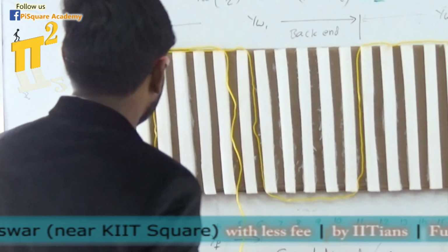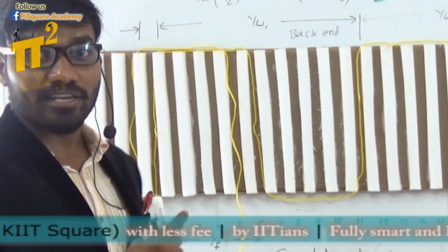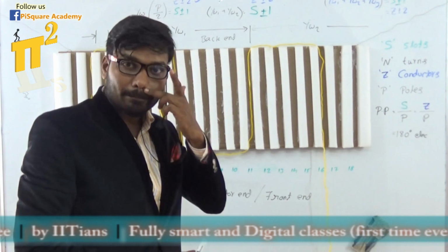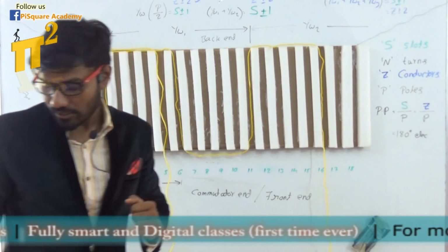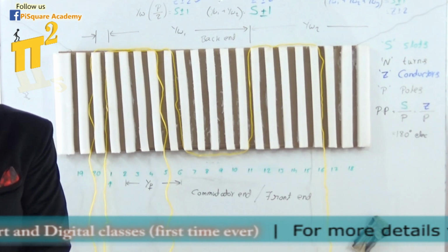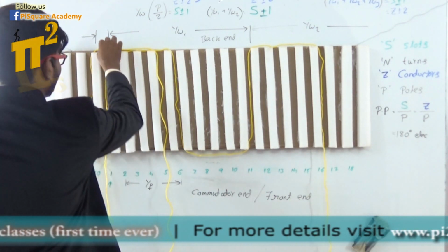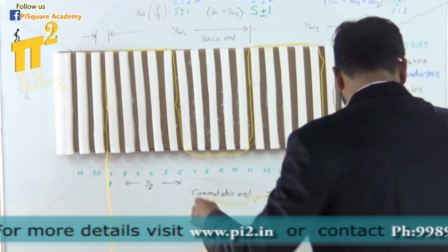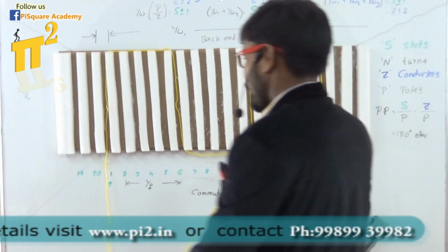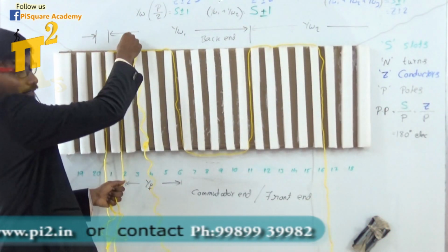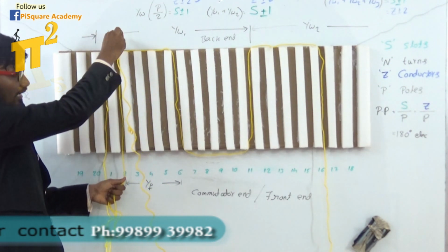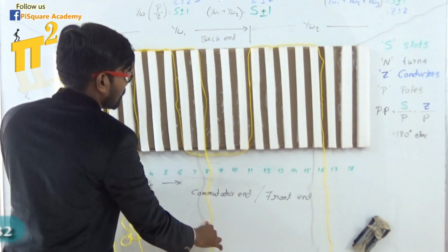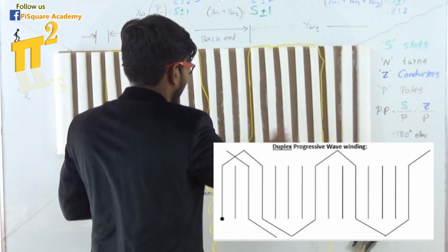Now, there is another thing called singly re-entrant and doubly re-entrant. But before we go to that, I think we missed multiplex winding. So far we have seen simplex winding. What is duplex winding? That's interesting. Okay. So here, what have we done? After that, either I continue here, right? So instead of putting it here, what if I leave 1 slot? I left 1 slot, I'll continue the windings.